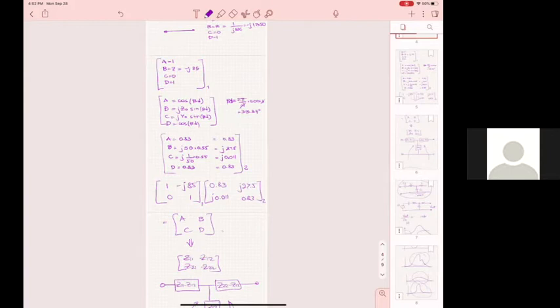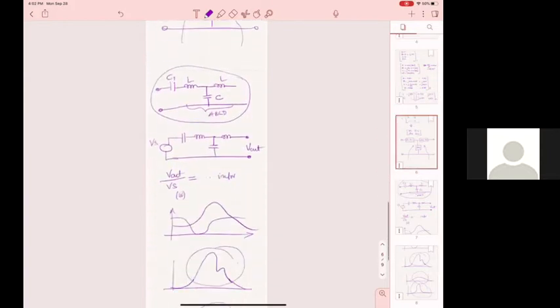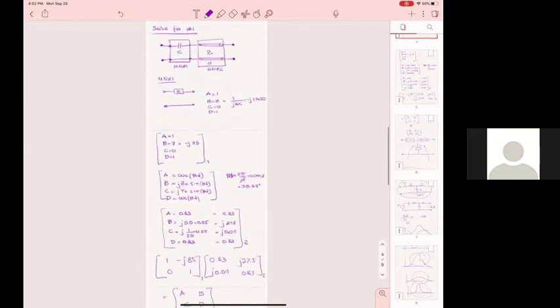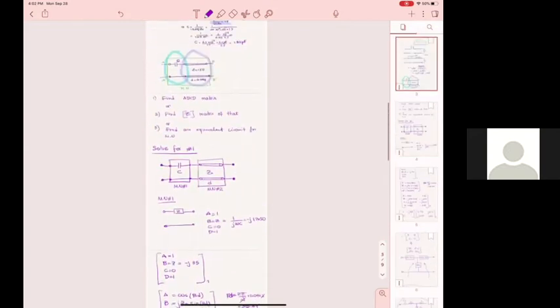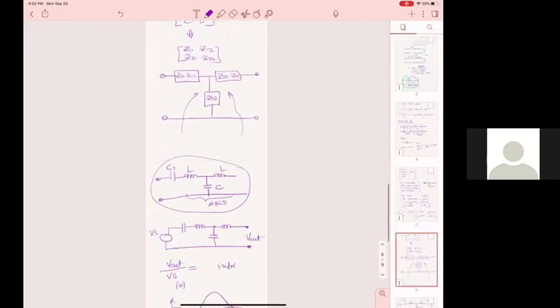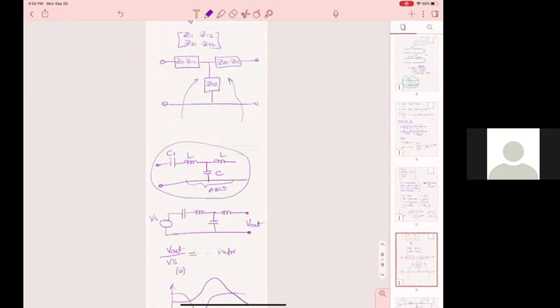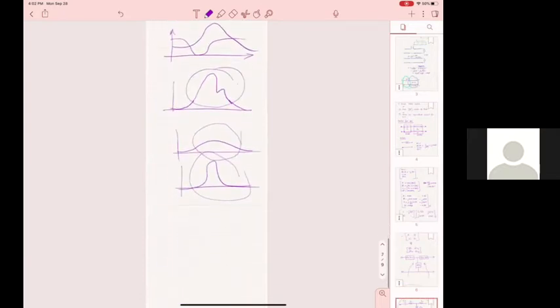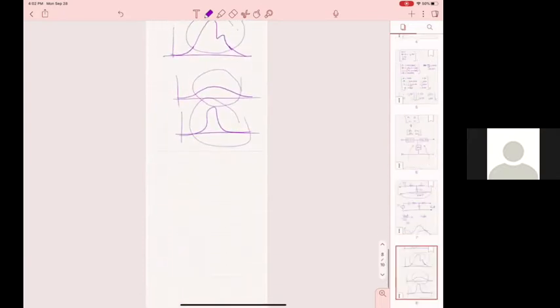And from what you were saying before, the transmission line equivalent, where it's an L and a C. Assuming that we're just taking the transmission line without cascading with anything else, it'll always give an L and a C, unless you include losses in the transmission line, and then it's going to give you some small resistors and a small conductance. So if the transmission line has losses, it's going to look like this.